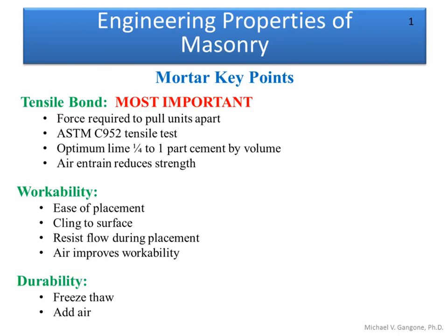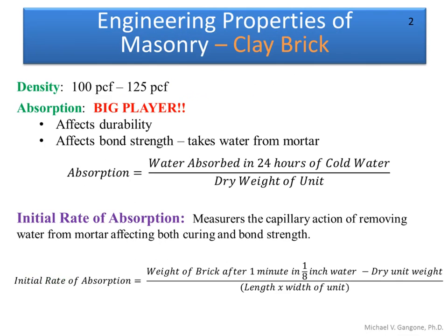But we also want to keep in mind when we're talking about the mortar, which is, again, what keeps the units together, workability and durability are also very important. So how easy is it to actually place the mortar where it needs to be, and also how durable is it? Can it withstand things like freeze thaw and other environmental effects? And sometimes you have to add air to help improve durability, similar to what we did when we talked about concrete.